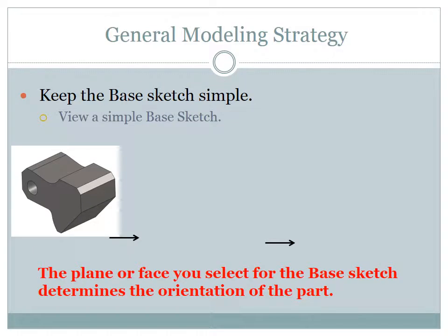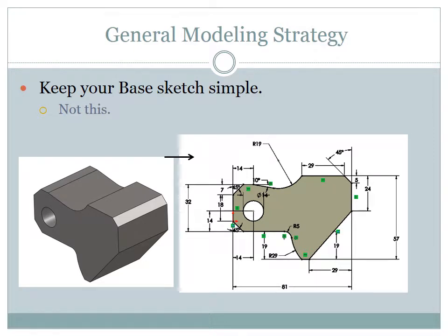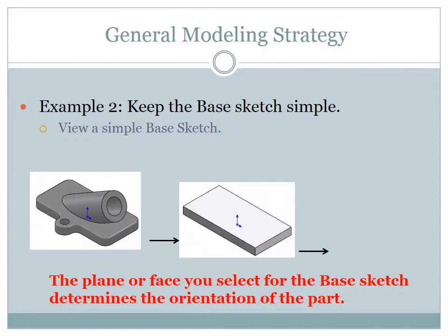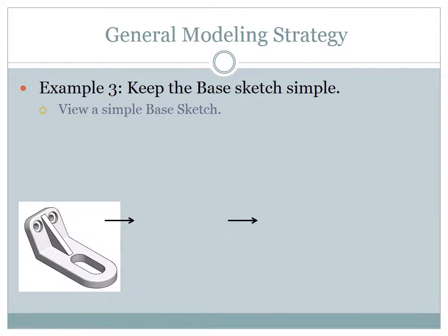Example of keeping the base sketch simple. Start with a block, cut away pieces. Another example of keeping a sketch simple. You could try and draw all that, but it's going to be a lot easier to start with a rectangle. Here's another example of keeping the base sketch simple. Start with a blank and move on from there.